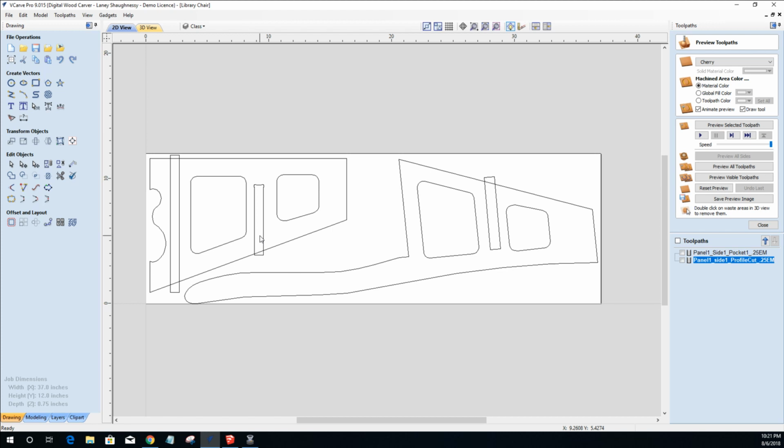Rockler, Woodcraft, it's a concealed hinge. Your boards are 3/4 of an inch thick, right? So the mortises for these hinges have to fit within 3/4 inch material. It'll actually say there on the page, recommended for 3/4 inch material or larger, or recommended for 1/2 inch material or smaller. We want 3/4 inch or larger material for our concealed hinges.